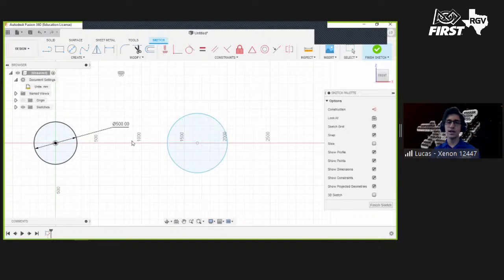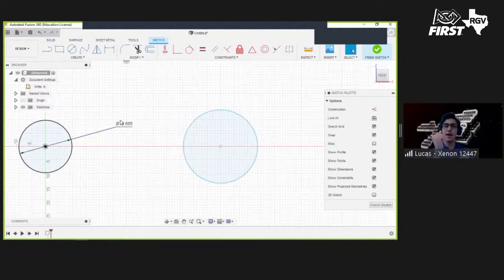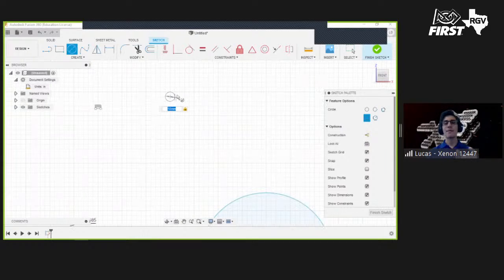You click inches, and now see automatically, what's really cool is that my dimensions convert from millimeters to inches, and now I'm no longer at 400 millimeters, but at 19.685 inches. It automatically converts. Something else I should mention: if you want to create a circle, for example, and I click that circle, I see how it already specifies inches. I can put a number in inches, 50 inches. And what's interesting is I can put IN, and it means inches. If I put MM, which means millimeters, it automatically gets super small, and it converts to millimeters.